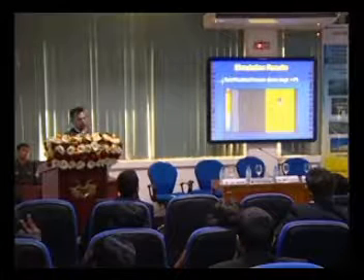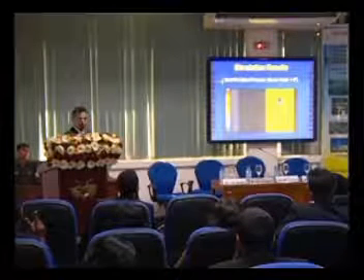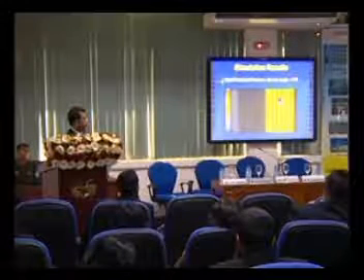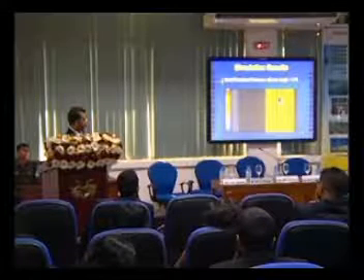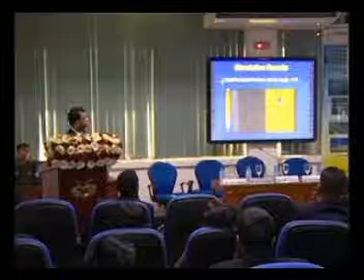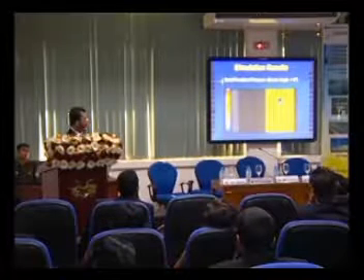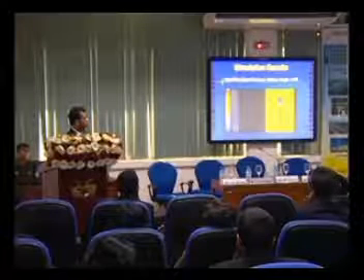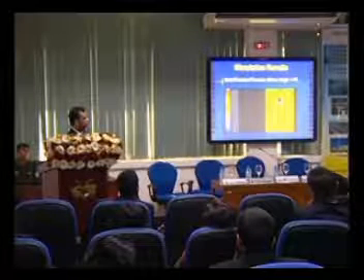So let me show you some of the simulation results. Total pressure, yeah. This is when the seam angle is 0. So you can see there is a symmetrical distribution of flow. So no pressure variation is there. So here we cannot expect any side force to take place.